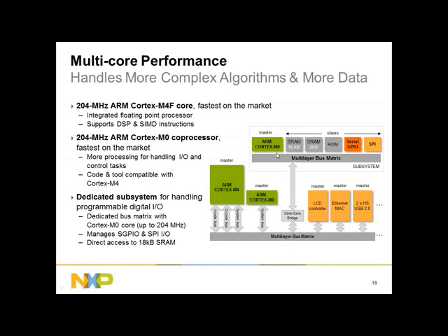A lot of times that's really important and helpful, certainly as you're interfacing to the serial GPIO or SPI. What's nice about serial GPIO is that it's basically 16 slices of I/O with shifting and clock register clocking, so you can create your own little interface that removes the need to do bit banging. Or at least, if you have to bit bang, you can bit bang on a 32-bit word boundary instead of a bit boundary, because you can fill it up with a word, and this extra M0 sitting on that bus can control the interface.